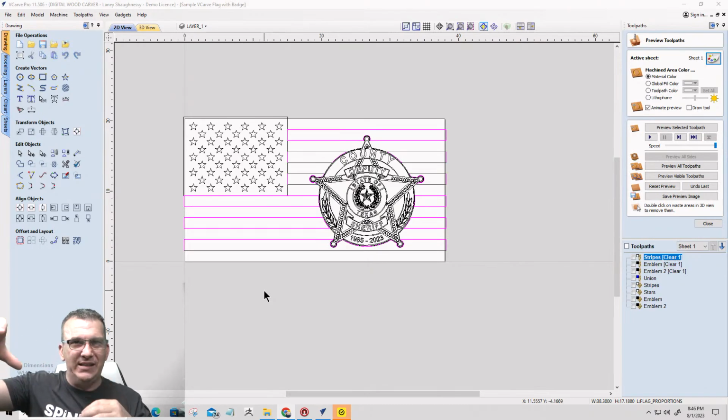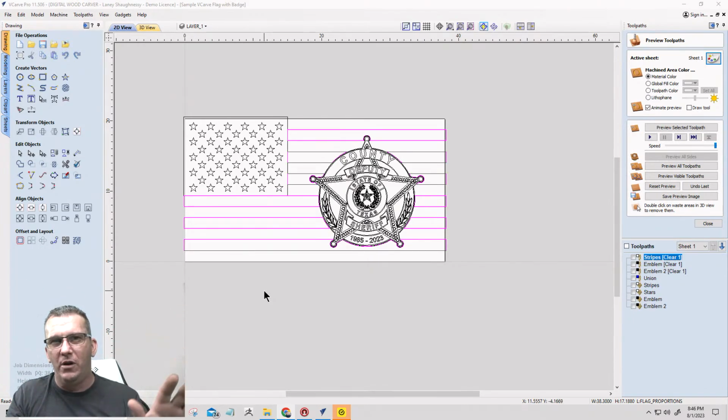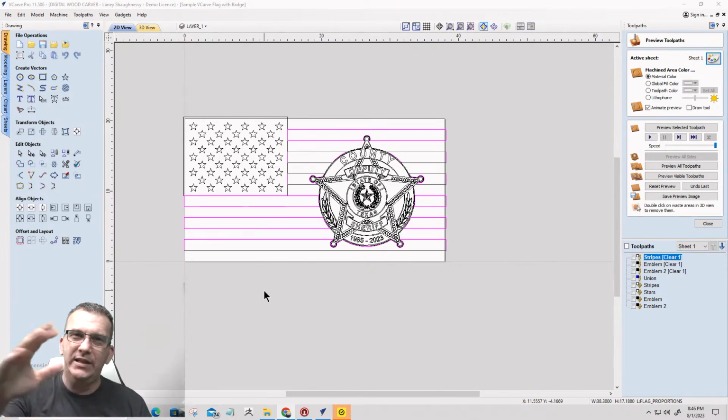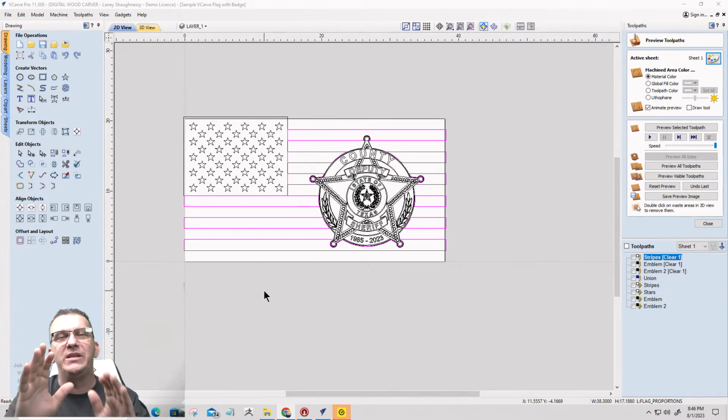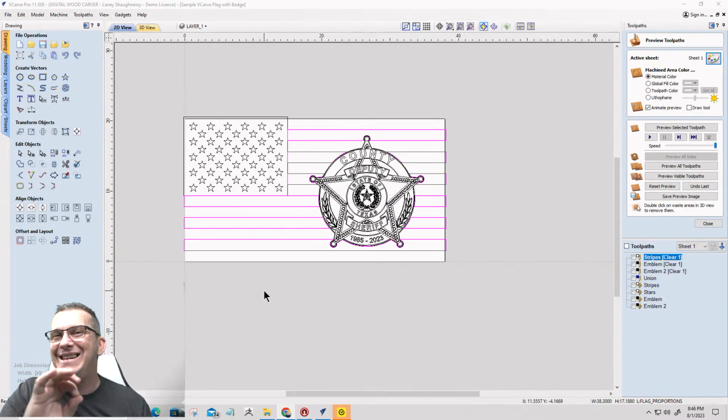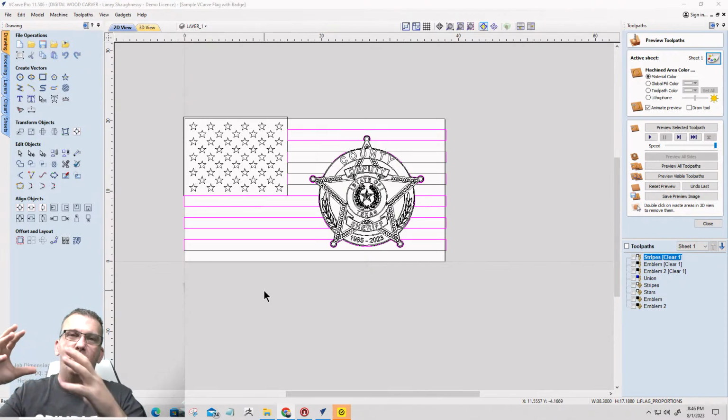You don't need to be at 6 for every tool that you do because you're running 24,000 for all those tools. Turn it down. If you look at any router bit company and you look at their specs for their tools, they are basing their specs generally off an 18,000 RPM setting. And in your case, we're going to be 18,000 or less.